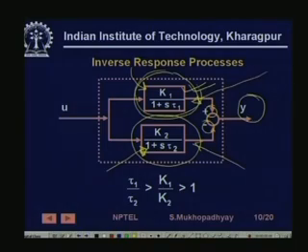It is called an inverse response process because the response to an input initially you see in an opposite fashion and finally you see in another fashion. So, if you design a controller for this process, then for the initial time scales the response of this will actually confuse the controller, and might cause instability and other things. This is the main problem.